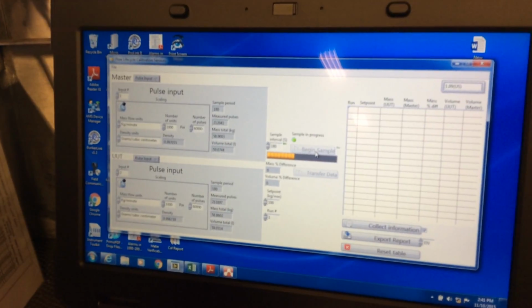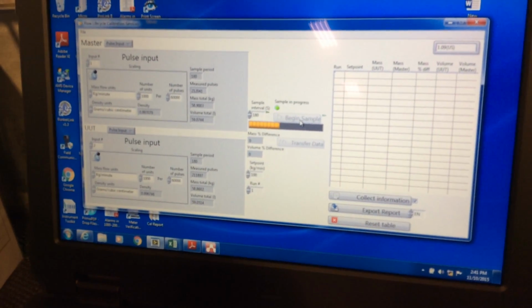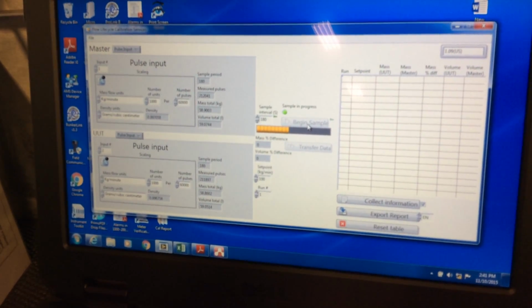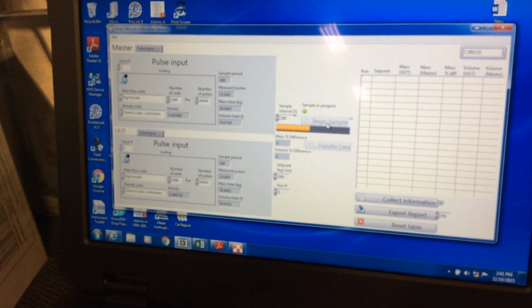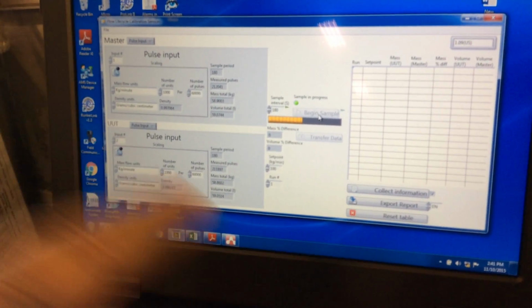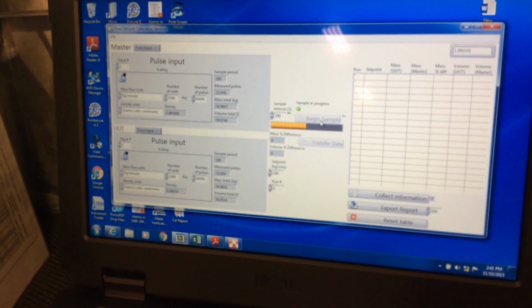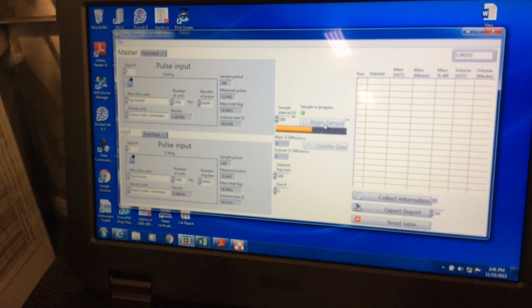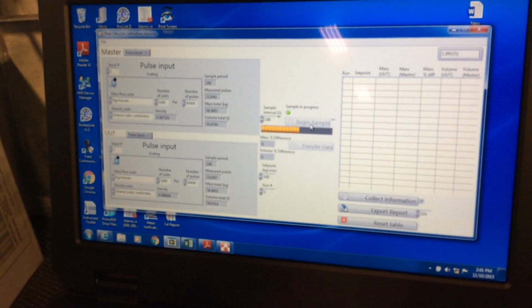You could export it and get that information, and it tells you whether it failed or passed, and then you choose not to save it or whatever. But each time it'll record all that information. And what I did is I did 3 pulls at, you know, whatever, 100 kilograms a minute or something, just to be doing it. And then I exported it and it showed that it passed. And I can show you that sheet too, so I saved it on this laptop.